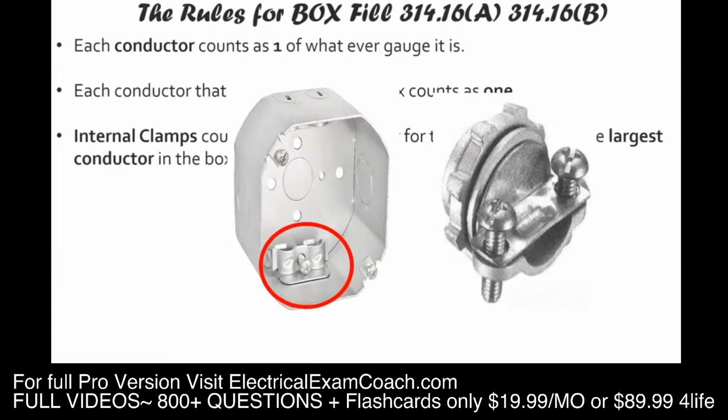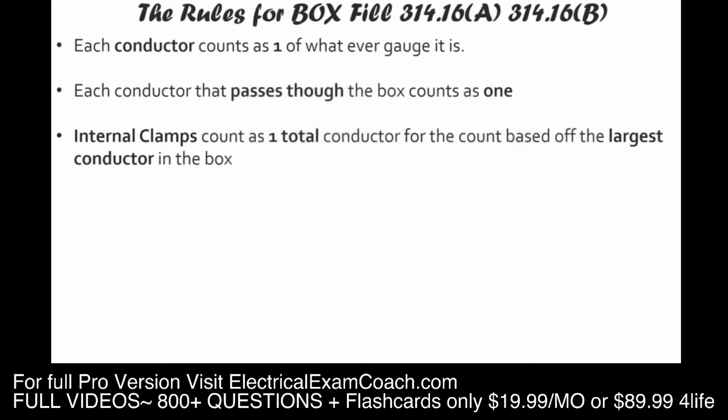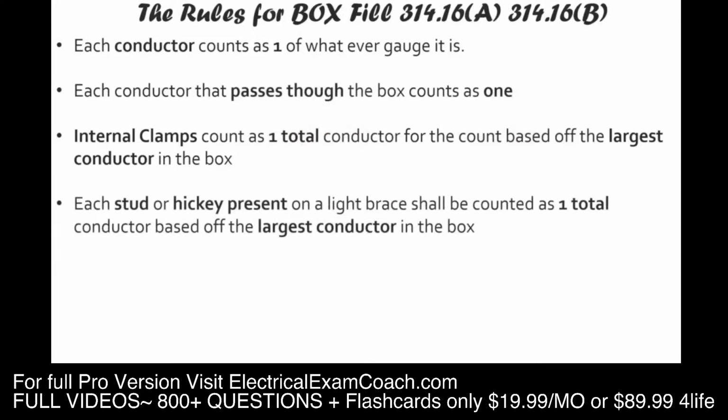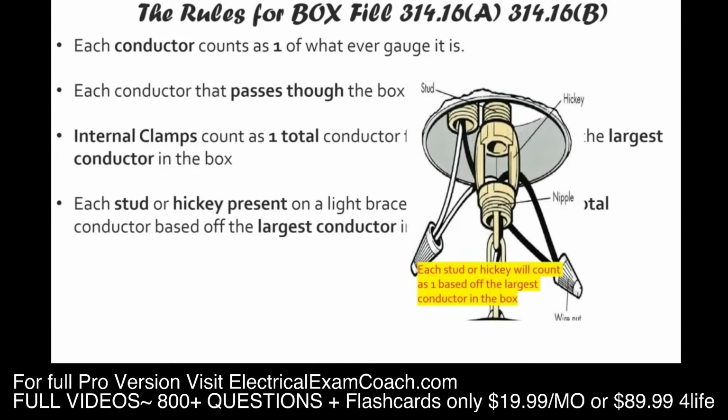This is an external clamp because the clamping mechanism is on the outside of the box, and we don't have to count those at all for box fill purposes. Next, each stud or hickey that is present in the box shall count as 1 total based off the largest conductor that's in the box. Now, these are really old words, probably from the 30s if I had to imagine, but they still use them on examinations today. And this is what we're talking about.